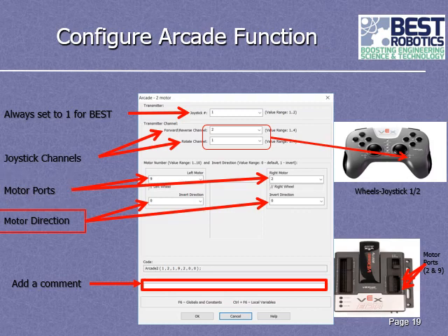The motor direction, typically you won't have to do anything here. If for some reason one of the motors was wired improperly or something and it was running opposite from what it should, you can fix that problem by coming in here and switching the 0 to a 1, which will then invert the direction that it moves. I don't really foresee you having to do it, but this is one place where you could go in and fix that spin direction so that it's the correct direction.